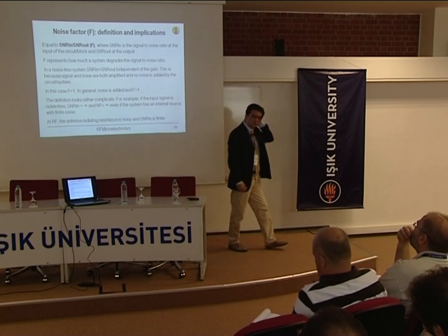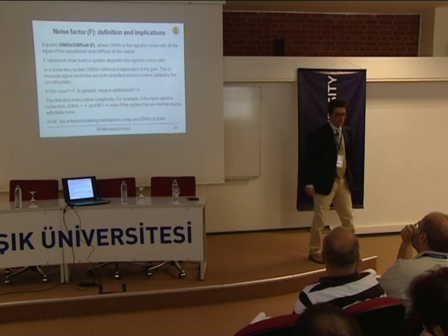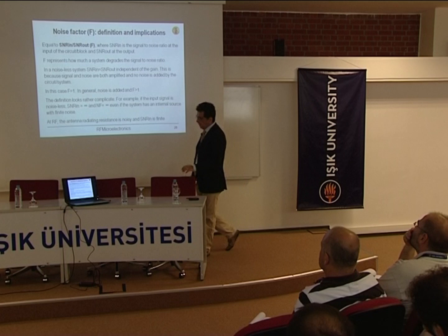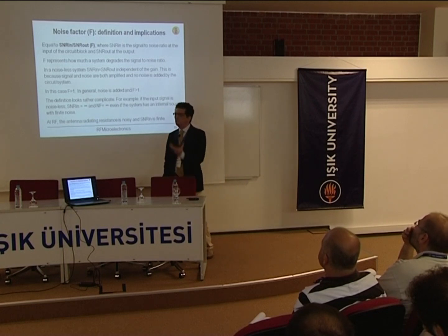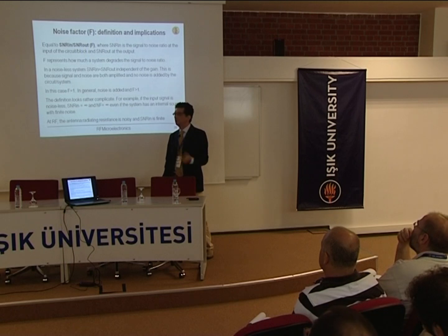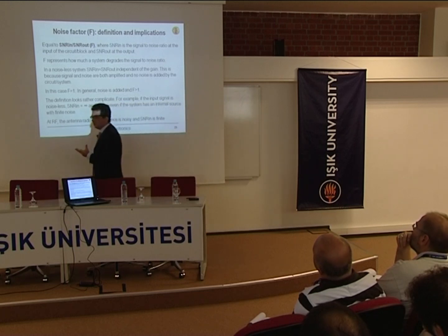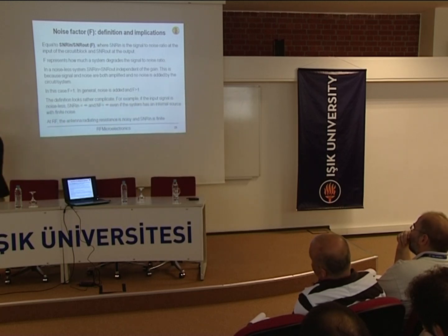And so when you design amplifiers in that framework, you are really interested in achieving the minimum noise you can, and you never use noise factor or noise figure as a metric. You're just interested in the minimum noise. When you do charge amplifiers for those applications, you usually talk about electrons of noise, so you're counting the electron equivalent of the noise.